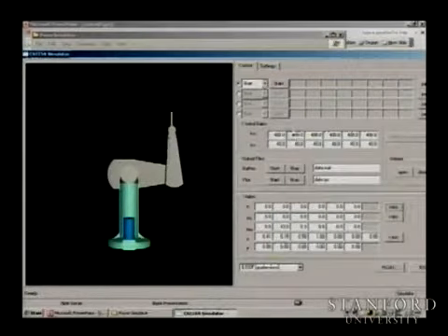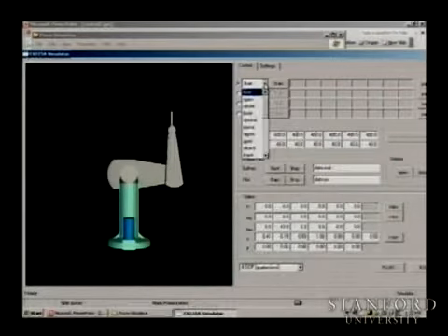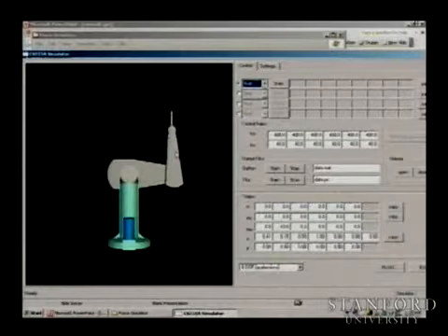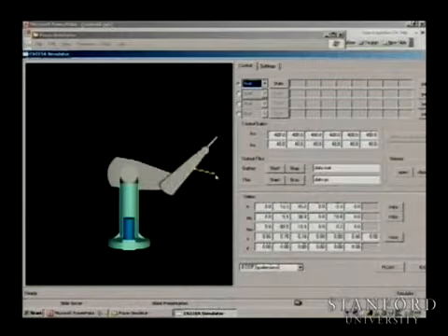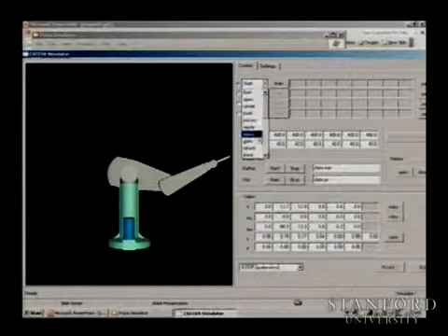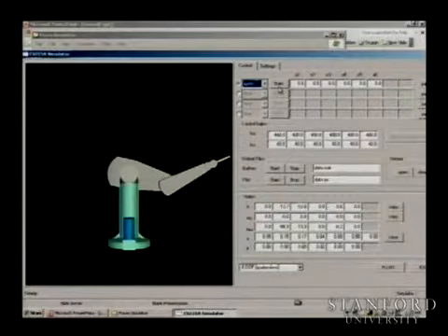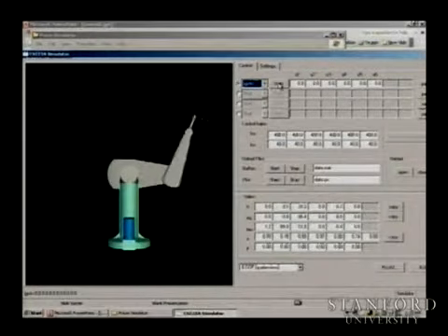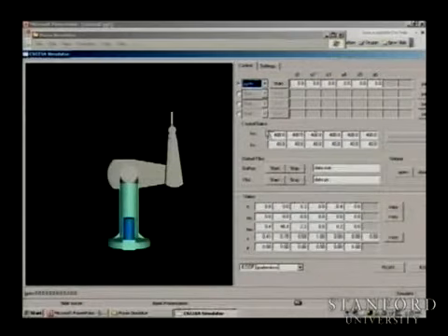Here are your gains, and right now the robot is floating, and if we ask the robot to go to its 0 position, it's going to just move. And it's moving with a Kp equal 400 and Kv equal 40. These are the gains we set for the robot. But in fact, this is controlled also with dynamics. So we will get to this a little later.